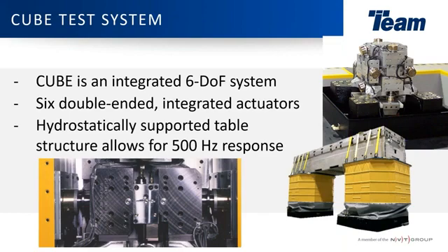And the pad bearing is essentially a spherical coupling that provides friction-free motion in the translational axes, as well as in all the rotations for which it's connected. By doing this, the cube box, the yellow component in the bottom right picture, is not mechanically connected to any of the actuators. The added benefit here is you do not have excess moving weight in different axes when you're trying to excite that payload.